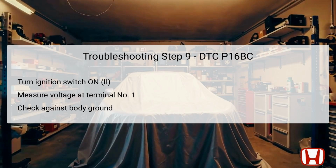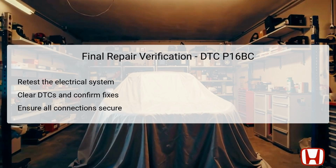Conversely, if there is no battery voltage present, it indicates a potential break in the circuit, which calls for further investigation into the wiring and fuses. After completing all troubleshooting steps and implementing corrective measures, the final repair verification is crucial to ensure the resolution of the DTC P16BC. Start by retesting the electrical system under the same conditions to confirm that the alternator is functioning properly and supplying adequate charge to the battery.